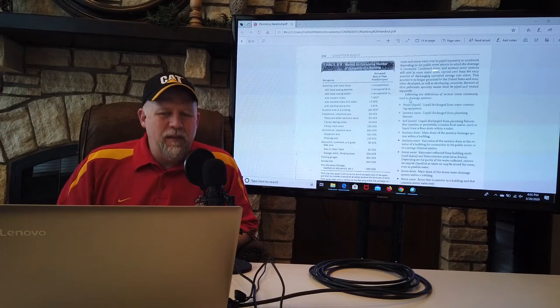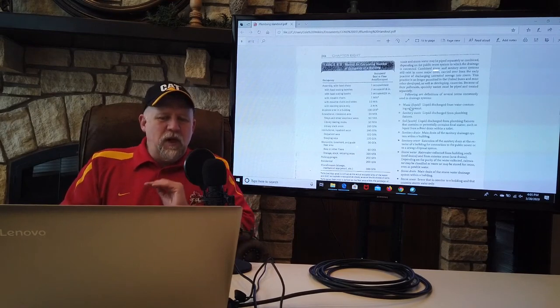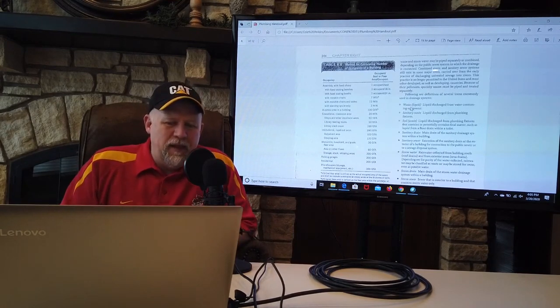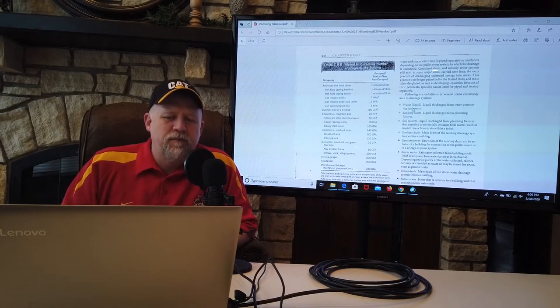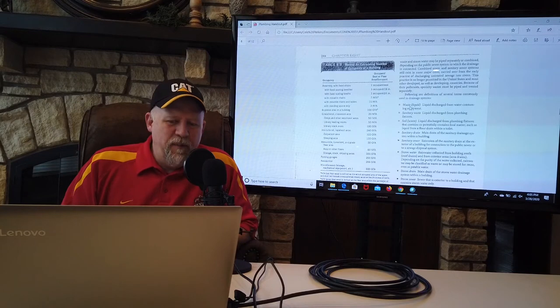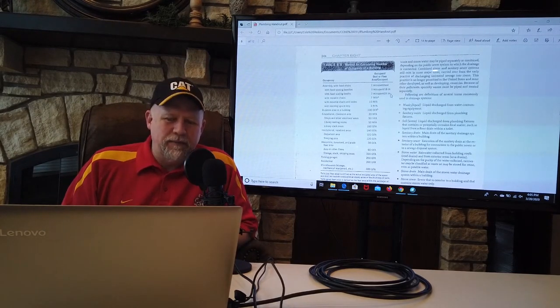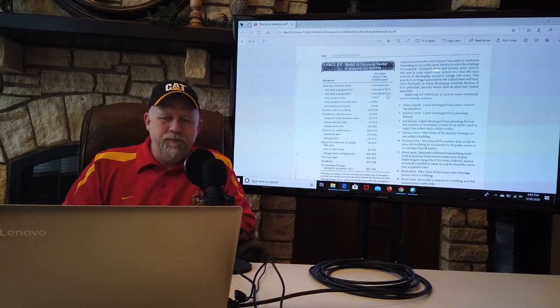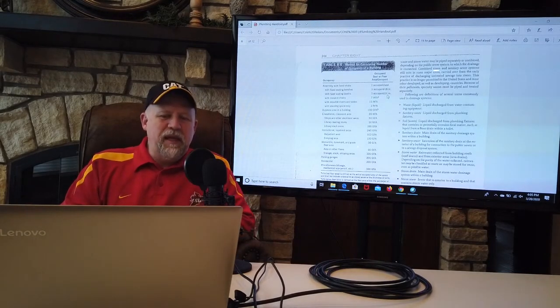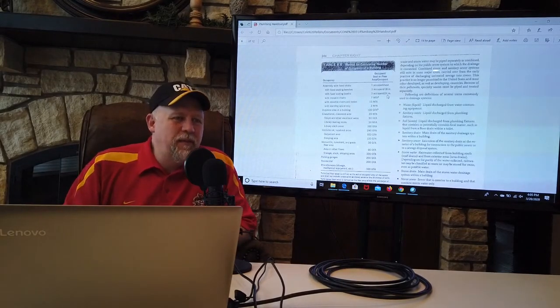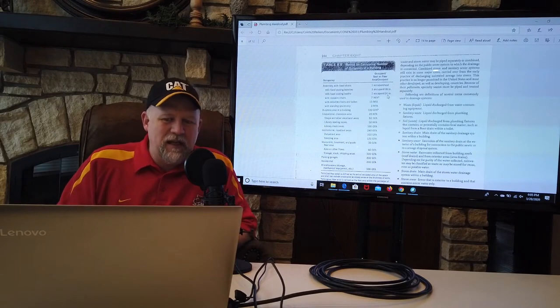All right, take a look at table 8.8. If you don't know the occupant number in a building, this gives you some rough rules of thumb to use about number of people per net free area of the building. All right. Assembly. If you have an assembly type of occupancy and it's got fixed seats in it, use the number of fixed seats.